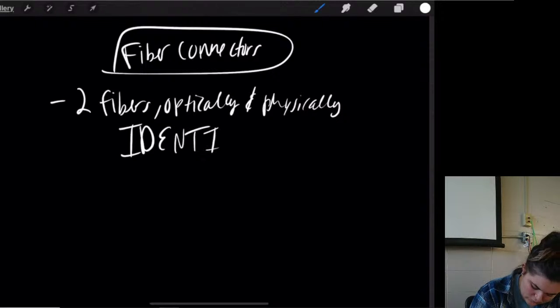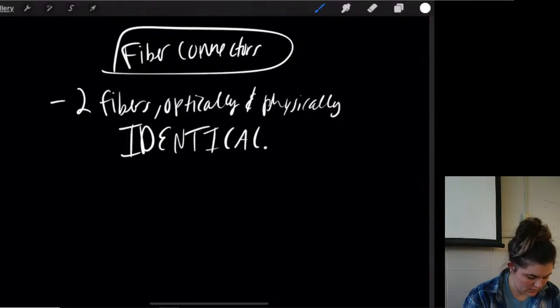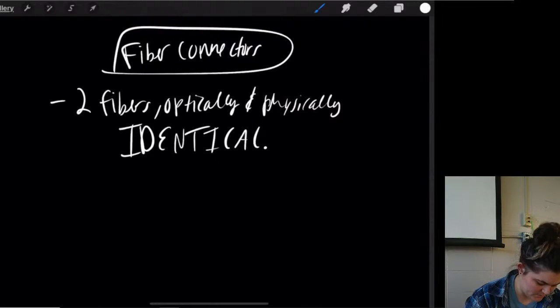Identical. These two fibers are held together by a connector or splice that squarely aligns them on their center axes. The joining of the fibers is so nearly perfect that the interface between them has no influence on light propagation. A perfect connection is limited by variations in fibers and the high tolerances required in the connector or splice. These two factors also affect cost and ease of use.